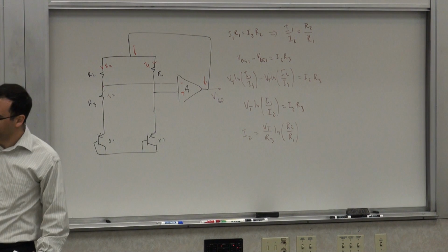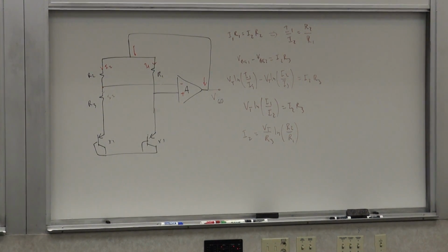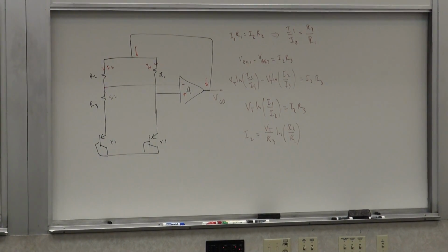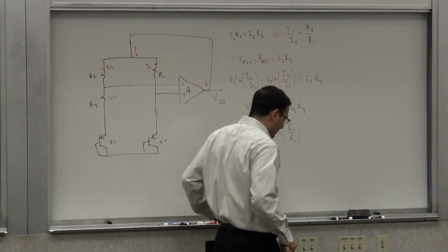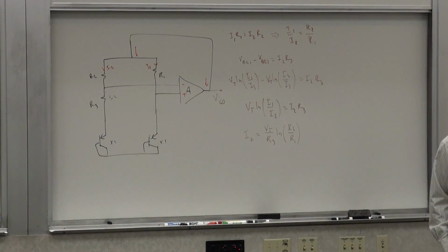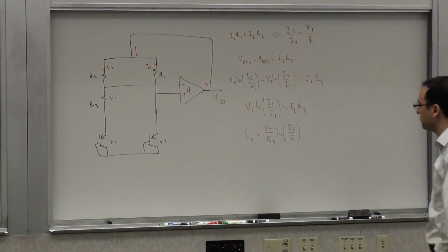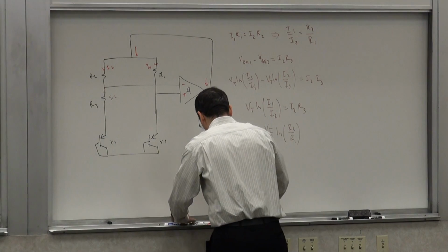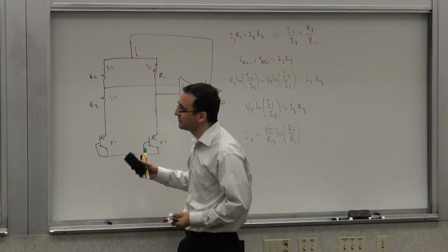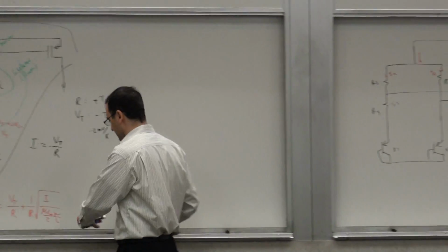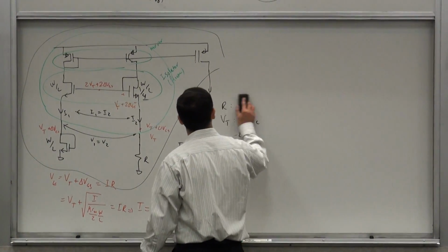Now, one last thing on this. Let's say you want to make an amplifier whose gain is independent of temperature. How would you bias it? Let's say it's a bipolar amplifier. So BJT. Let's say you're making a differential amplifier. You could bias it with the bandgap current source in such a way that its current is constant. You could bias it with a constant current.